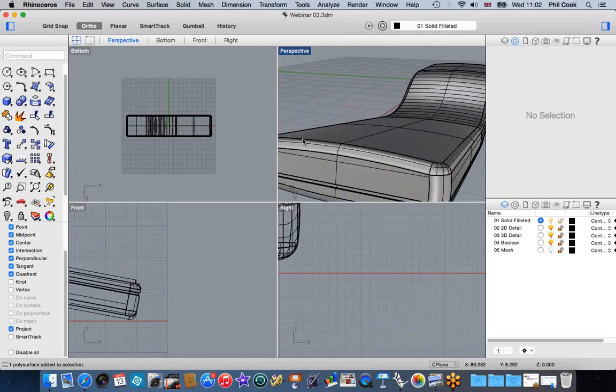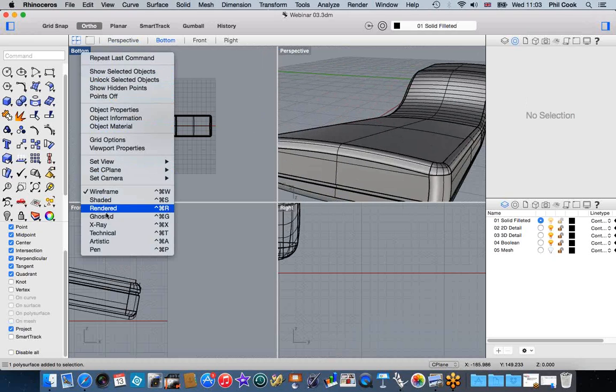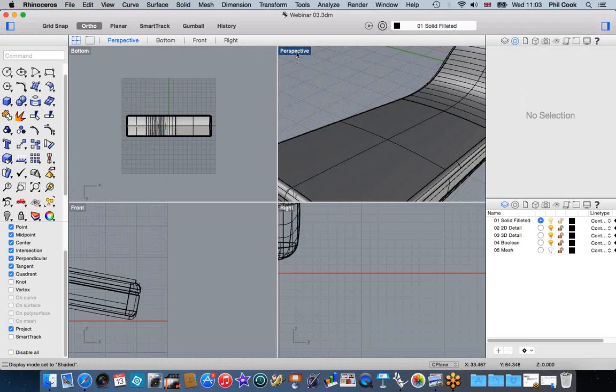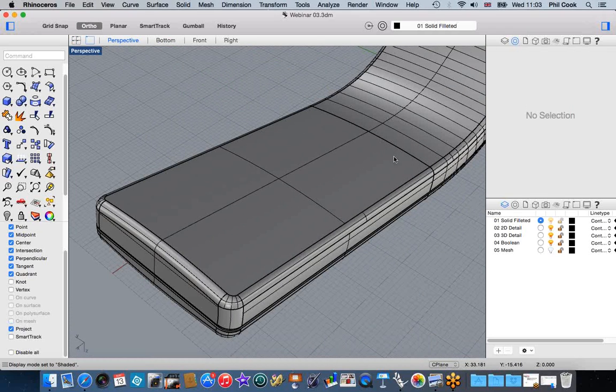These faces themselves have curvature to them, so it's not immediately straightforward to add detail onto curved surfaces. So what we're going to do is to actually model the detail on a planar surface and then use a Rhino transformation command called Flow Along Surface to orient the objects onto our curved surface. This is a particularly effective way of creating detail for concept designs. So if I just maximize this view here, let's take a look at this surface first of all.